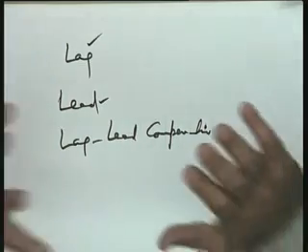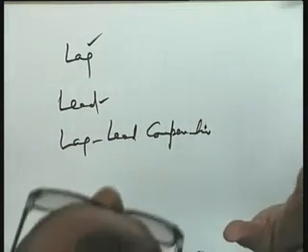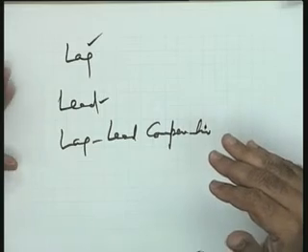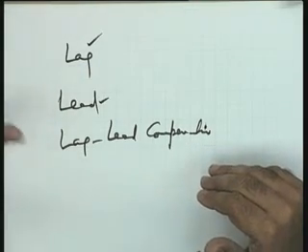Please see. Now the standard procedure will be like this. This is the standard final procedure. You simply investigate your open loop system very carefully. You do the gain adjustments, see the transient performance. If the transient performance is satisfactory, the choice is lag. Okay, you will not require lead. Decision has been taken. If the transient performance is not satisfactory, you go for lead and make the transient performance satisfactory. Okay, lead compensator has been designed.